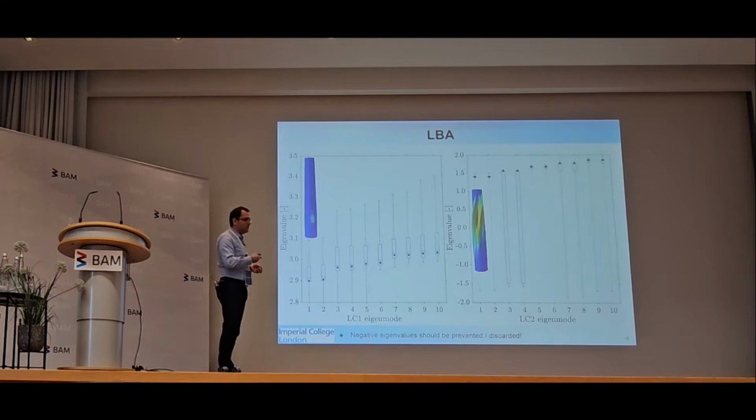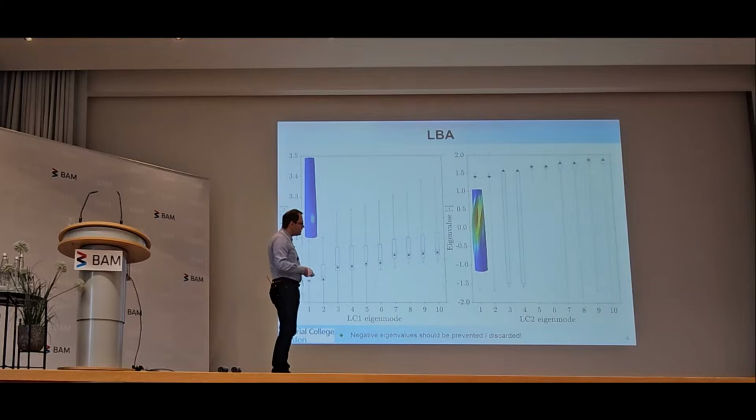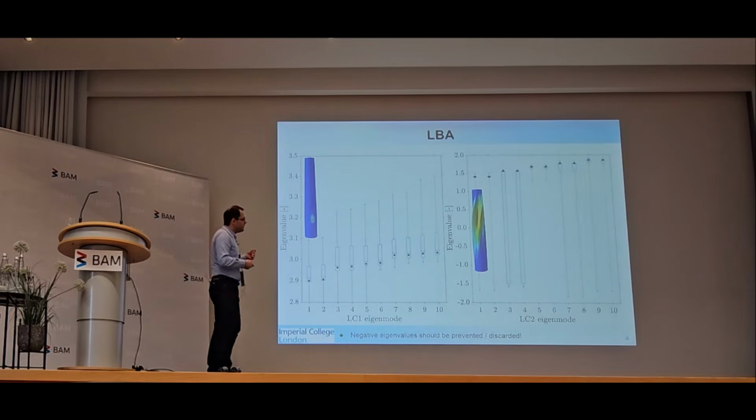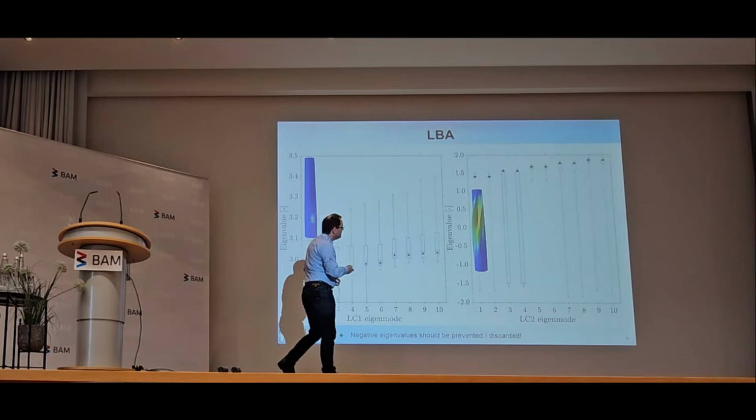And that means that there is a critical eigenmode whose absolute value is similar to the critical one, but it has a negative sign. And many submissions reported this negative eigenvalue as the critical mode. This is not correct, because negative eigenvalue means that all of the loads are acting in the opposite direction: the torque, but then also the transverse shear and the moment, and your vertical load now acts upwards. So it's an incorrect state.